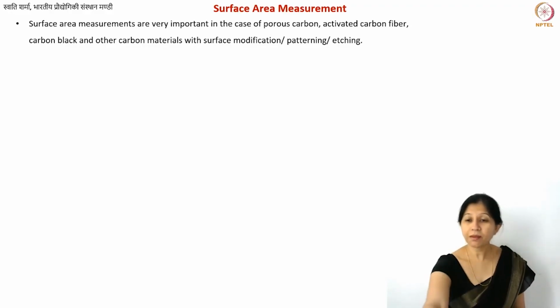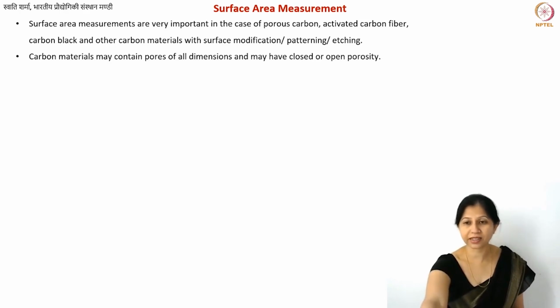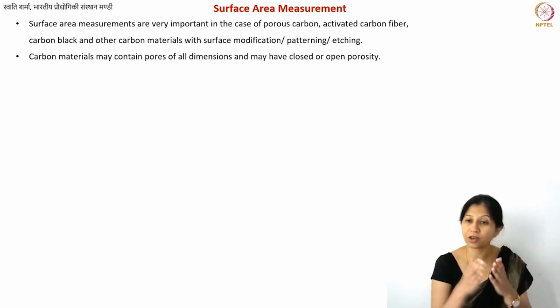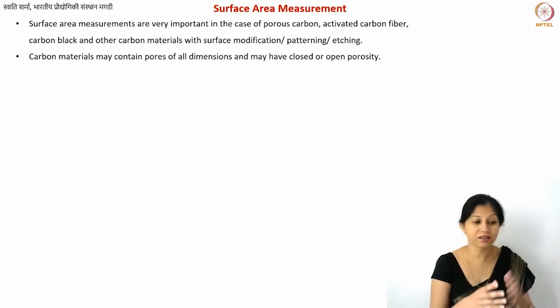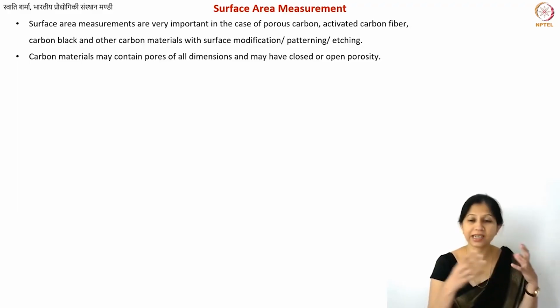But in general, if the porosity is increased, often the surface area also increases, especially in the case of activated carbons, because often a lot of pores are connected, percolated. Also, if you remember that we talked about these fractal-like geometries, which means you have larger pores, smaller pores, even smaller and smaller. So you have the porosity very nicely distributed in porous carbon materials.